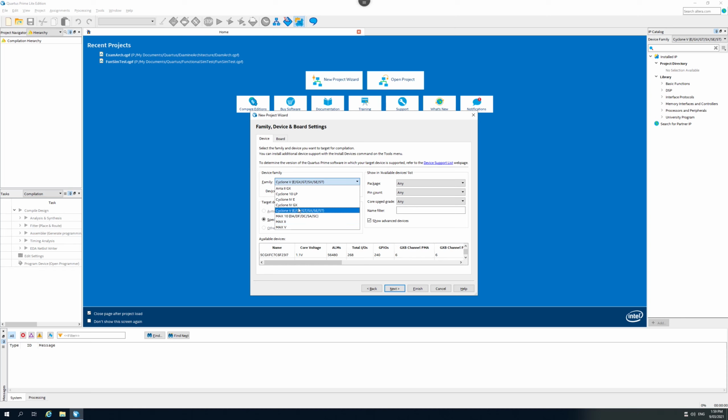So on the DE1 SoC board that we're using, when you power up that board, if you want it to remember the old code, you actually have to configure some external hardware that's also on the board to reconfigure that FPGA each time you switch the board on. A complex programmable logic device is able to remember its configuration, so you don't need to program it.